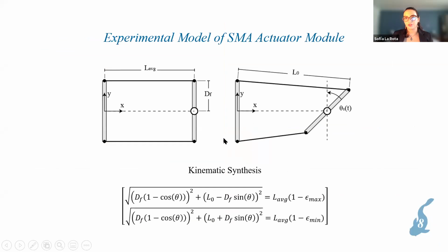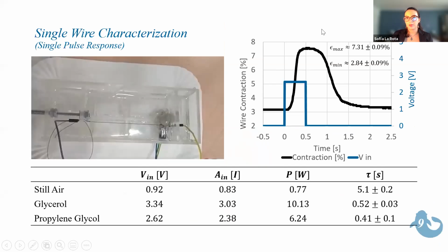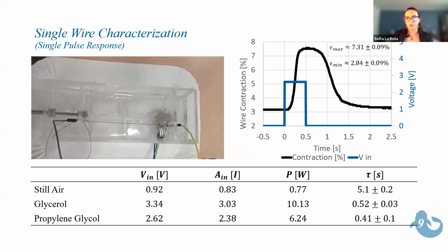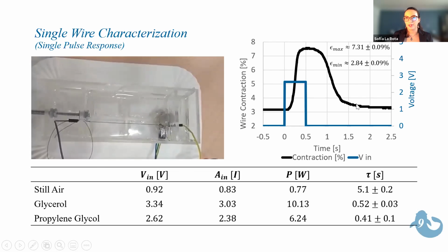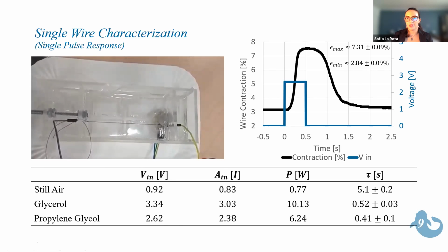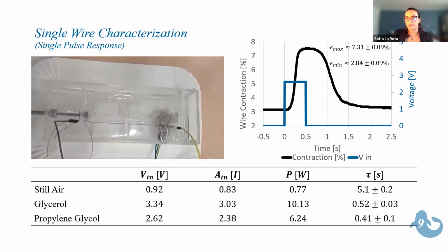Yes, your question is extremely relevant. And that is why, for example, if we see in this module, if this wire contracts faster than this wire can expand, the excessive strain is, of course, going to fatigue the wire. That is why this experiment was conducted in order to find a suitable response time so as not to overstrain the metal. But of course, I did not really analyze this phenomenon for an extended period of time, so I could not conclude on results that could take more time to develop.